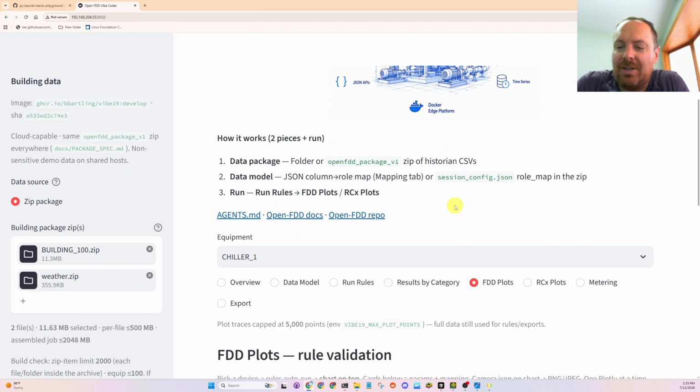I don't think there's much I can do for the chiller here because I'm only looking at 2 sensors, basically supply and return chilled water sensors, and validating that they're within tolerance of what a chilled water sensor should be, and then degree per hour changes.